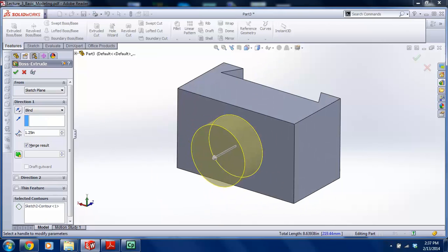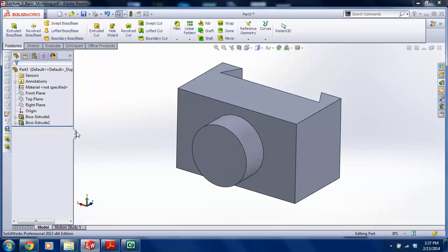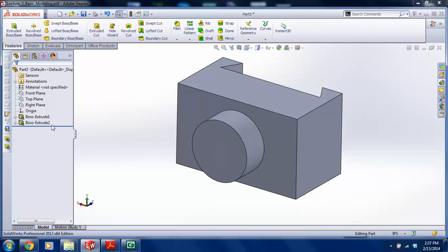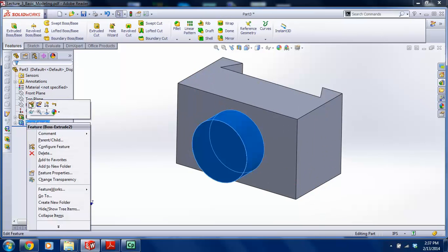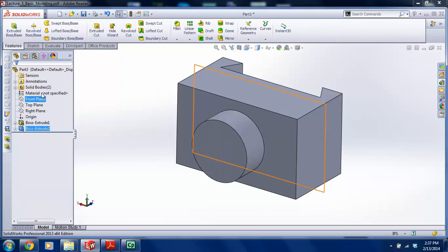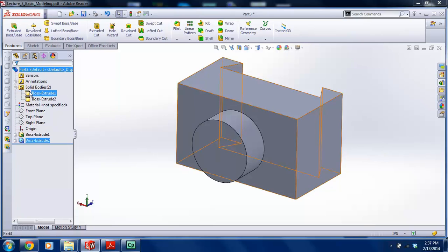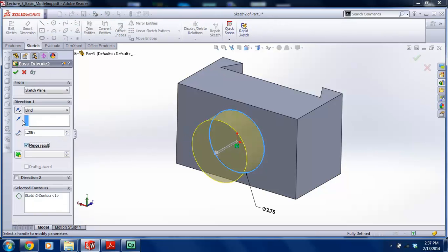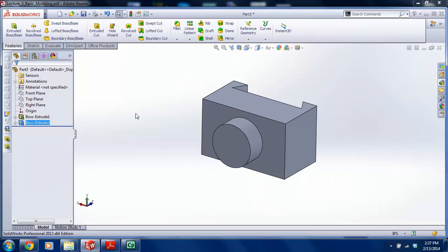Let's rotate, it looks good. Let's make sure we merge them. Let me show you. If I don't, well, no, I'm not going to show you. If we don't merge them, sure I may as well. If I don't merge them, let's see what happens. I'm left with two solid bodies. I have that solid body on that solid body. There's really no point. You typically want to merge your features together. I don't think I've ever needed to have separate parts.